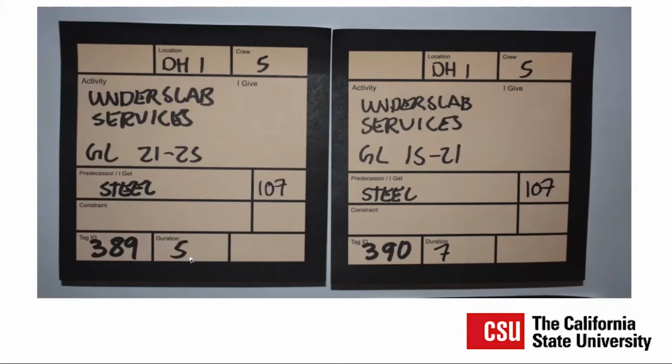One thing to note on this is sometimes trades may want to go long periods of time. If you go beyond, we like to say, 10 days duration, 10 days is kind of the maximum. Anything longer than a 10-day duration can be broken into smaller chunks of work. So electricians, if we've got any electricians or electrical contractors on the call, I apologize in advance, but electrical contractors and the foreman a lot of times want to go with longer durations because of the way they're thinking about how they're going to do their work. But they can break that down into geographic areas, or whether they're doing their main runs and secondary runs, and then pulling wire and terminating. There are different ways to break their scope of work down.